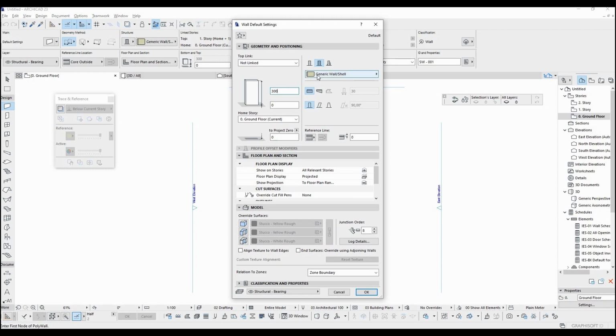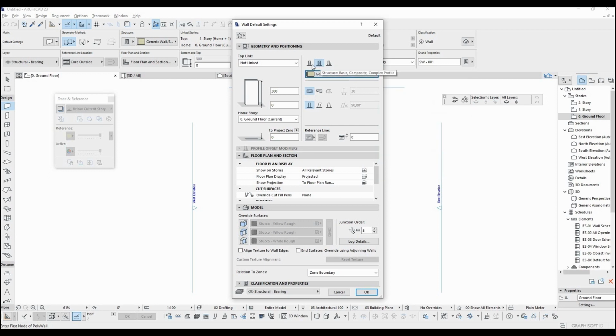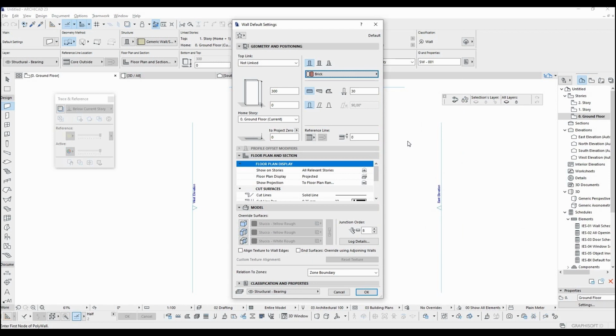Here in this part, you can change the complexity of the wall. You can use any of those prepared before, or you can make a composite wall type too. I will make another tutorial for composite walls. But before that, here we can see the structural types. We just select or make a structural type for our project: glass, wood, concrete, etc.